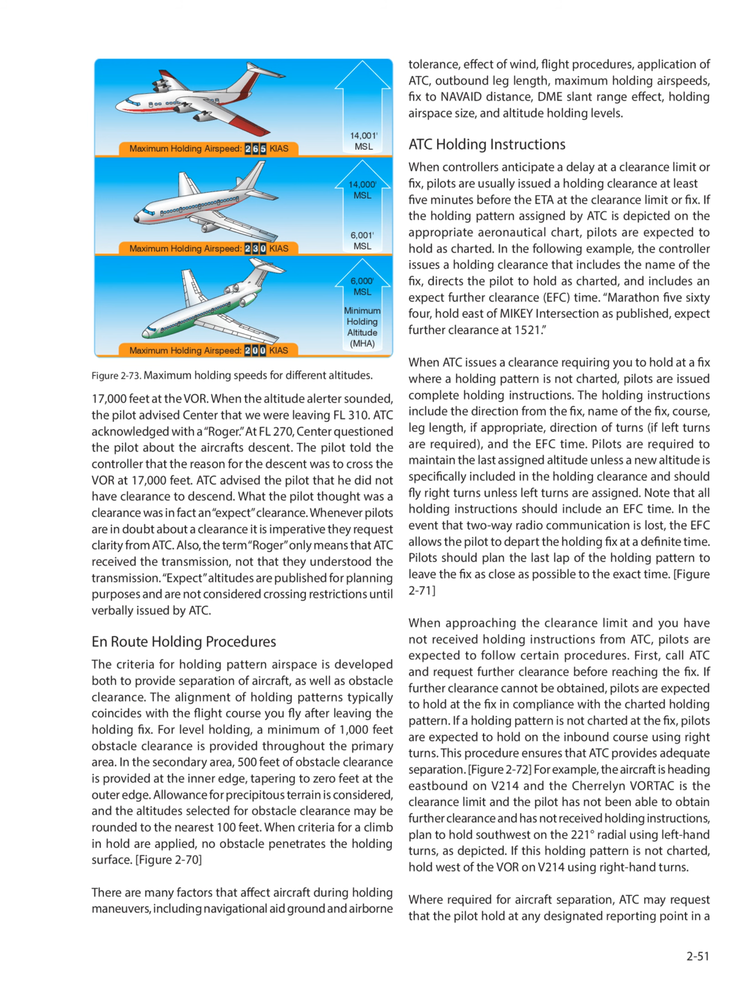In the event that two-way radio communication is lost, the EFC allows the pilot to depart the holding fix at a definite time. Pilots should plan the last lap of the holding pattern to leave the fix as close as possible to the exact time. Figure 271: when approaching the clearance limit and you have not received holding instructions from ATC, pilots are expected to follow certain procedures. First, call ATC and request further clearance before reaching the fix.